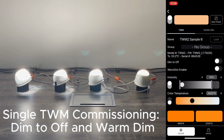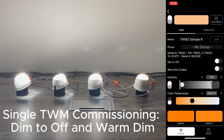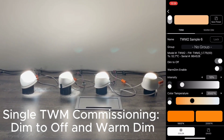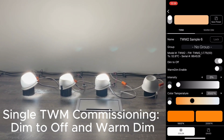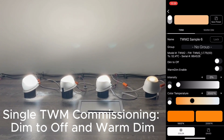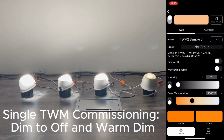What we can also do is change a couple of the special parameters on the TM2 unit, including dim to off and warm dim enable. Assuming that you have a trim for the unit itself, you select this toggle for dim to off right here, and then when you dim up and down, instead of going to 1%, it turns off, like dim to off. And if you untoggle it, then when you dim up and down it just goes back to minimum dimming as well.